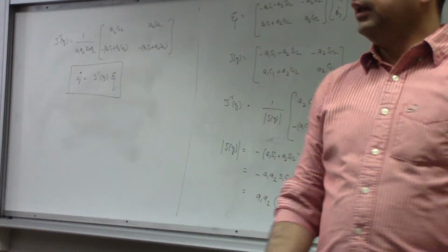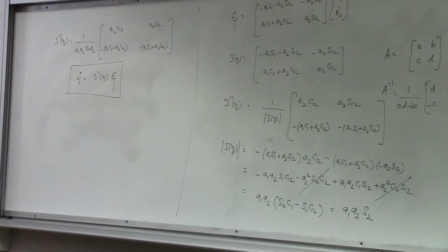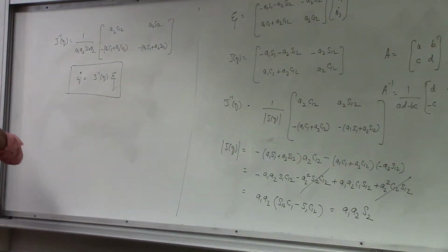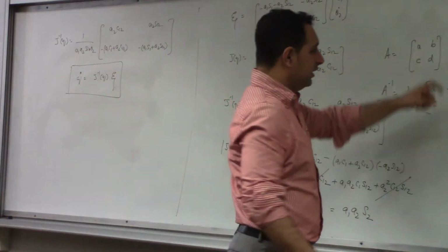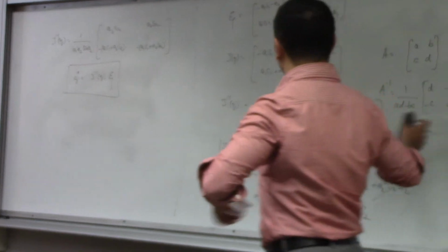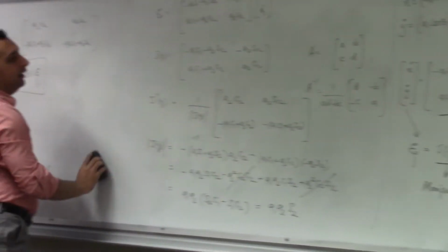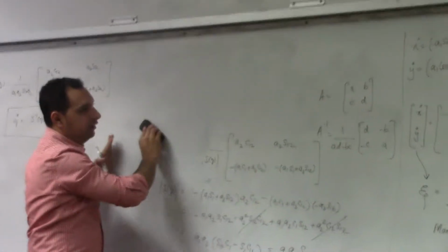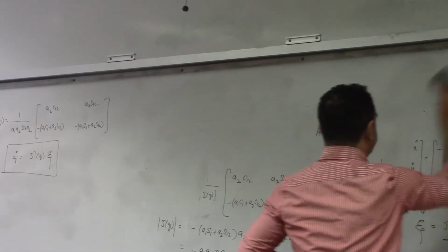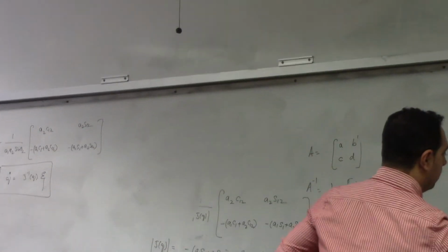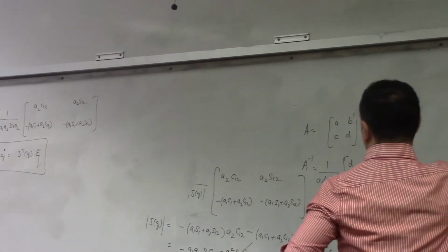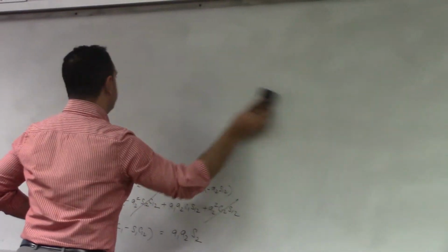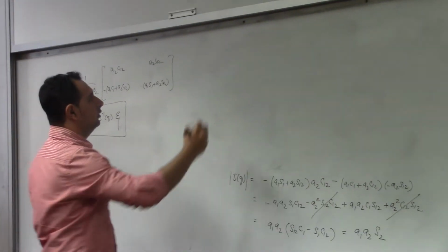Now as you can see, this is a simpler way to do it, only if the manipulator has a very analytical form of a forward kinematic equation that you differentiate. Now you can see here that you have theta 1, theta 2. When I differentiate this, let's say you have 6 thetas. It becomes rather tedious to do this. So you need a more general approach to developing a Jacobian. So what we'll do is we'll try to figure out a way where we can write the manipulator Jacobian by looking at its DH table. Alright, so we'll take a general approach to finding the manipulator Jacobian. Okay.